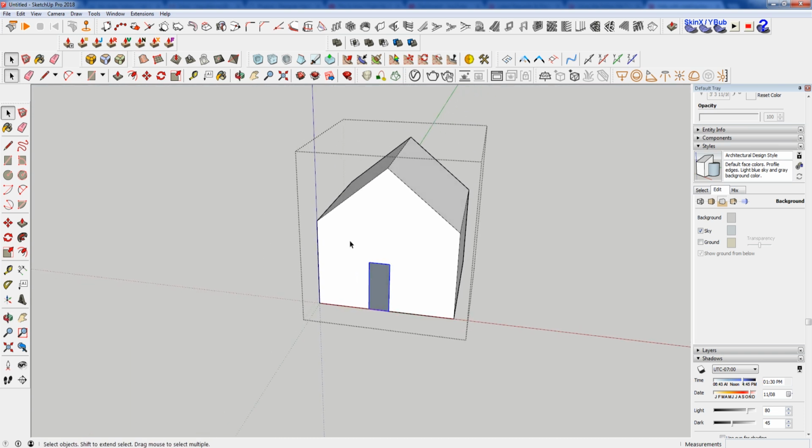And it's also important to know that the direction that you select matters. I selected from the top left to the bottom right. That'll select only the instances that are fully within my marquee, that box that I'm making. If I was to go from the bottom right to the top left, it'll select everything that my marquee touches. So you can see that's a very different selection. And you'll need to know when you want to use which.